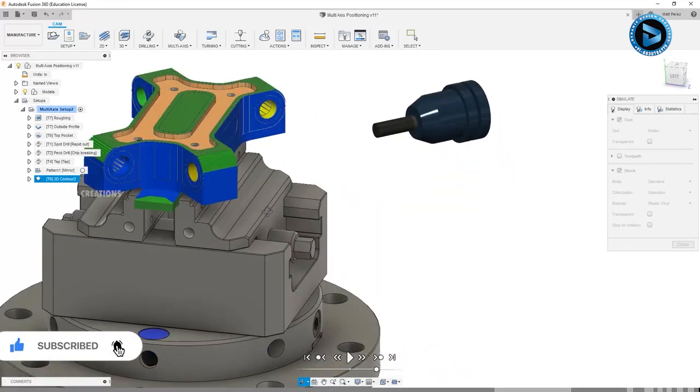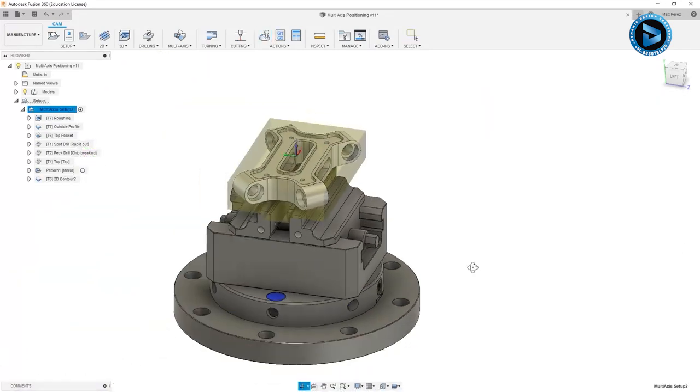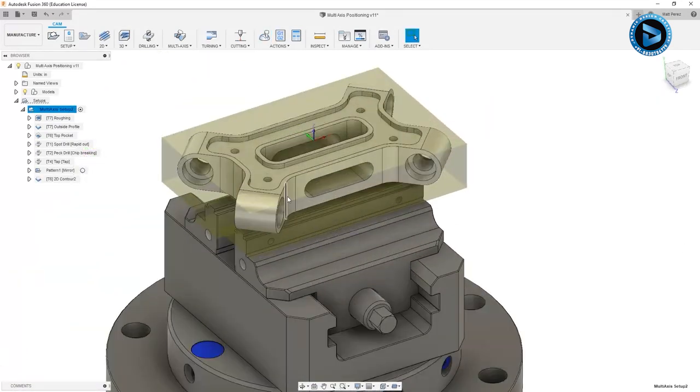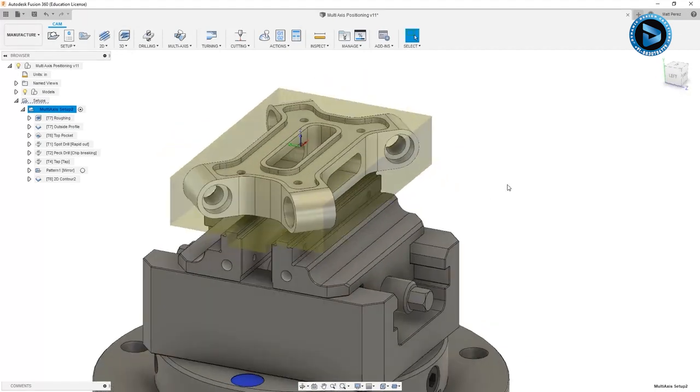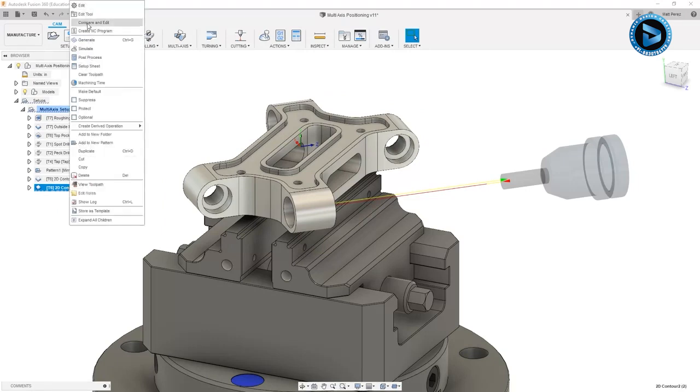Now we just need to repeat this process on all sides of each of these mounting positions. Because we did that first operation on this position, we can go ahead and take care of it by mirroring this operation. However, it gets a bit complicated because we won't be able to mirror the mirror pattern. So we want to make sure that we create all of the positions as needed, and then we can go back and create that mirror. So what I want to do is right click on this and duplicate it. Then I also want to make sure that we edit the duplicate.